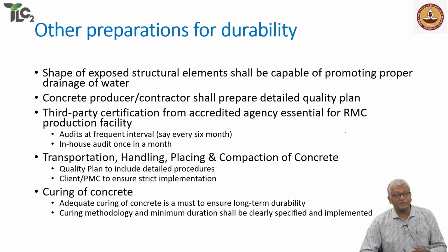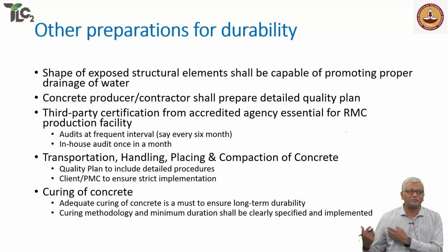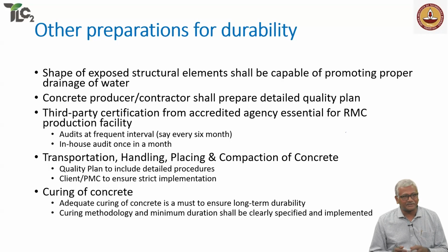There are several other preparations that are necessary to ensure durability. One is obviously the shape should be capable of promoting proper drainage of water. It's funny that I should even write this because it's common sense, but unfortunately, in many of our situations, this is one aspect that we don't seem to follow, including in our building science block ground floor slab. The previous design was such that the water which came in because of rain stayed there.